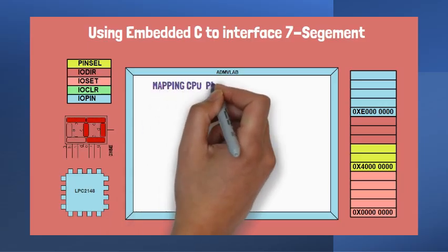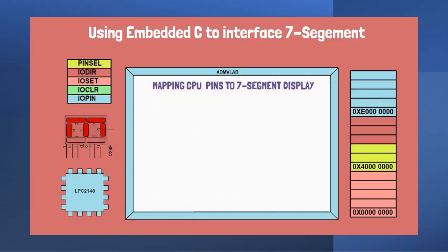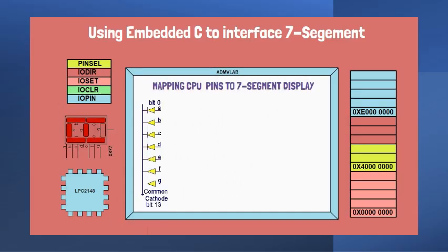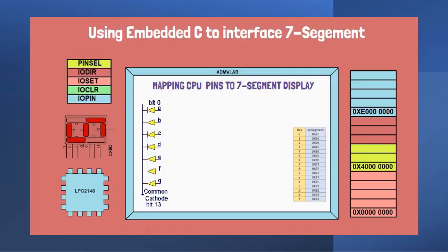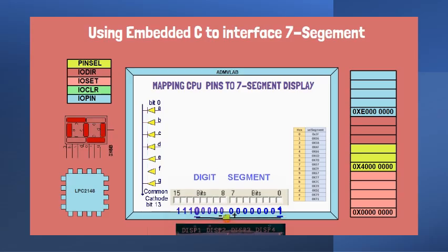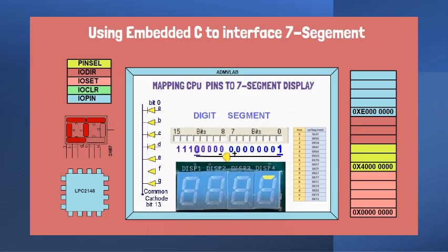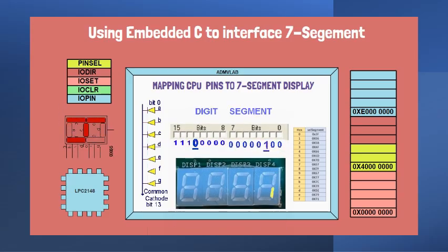7 segment display is an arrangement of 8 light-emitting diodes used for displaying alphanumeric numbers. The diode equivalent circuit shows all the cathodes, or negative terminals, of the segment LEDs are connected together and grounded. We can produce a truth table for each hexadecimal number. The animation displays the possible binary values when each individual segment is lit.